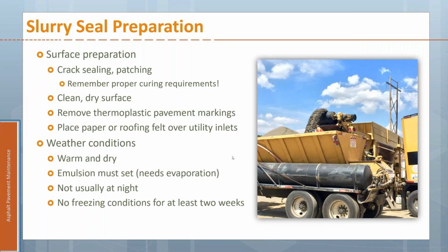This is another activity that you want to do in optimal weather conditions. This is a warm and dry summer type thing. Your emulsion's got to set. It needs that evaporation, so sunshine and warm temperatures is definitely going to be a help. This is not usually something that you want to do at night, primarily because your emulsion is going to take a lot longer to do what it needs to do with curing. You also want to make sure you have no freezing conditions for at least a couple of weeks after you've placed it.